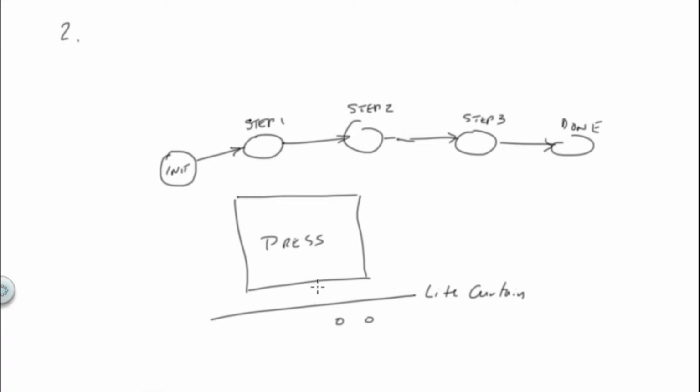But then I walked inside the light curtain just right here, and guess what happened? It took off on me, which is something you don't want to have happen, because you want me to have to come back out here and push the buttons again in order to reinitialize it. So many times you have to ask the question, if there is a process stop, how do you restart? This was not a good thing for me, and I immediately went back and put that in the logic to allow that to only happen. Now, if I were to do that today, I would do this with a safety PLC.